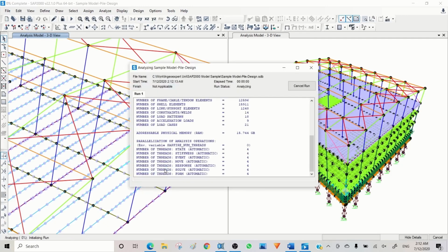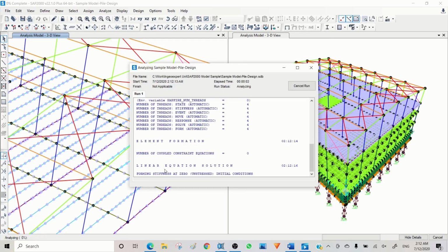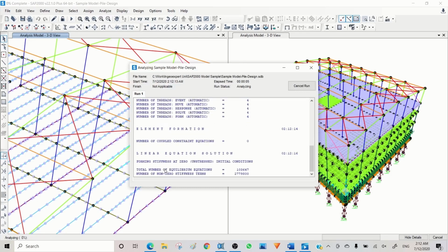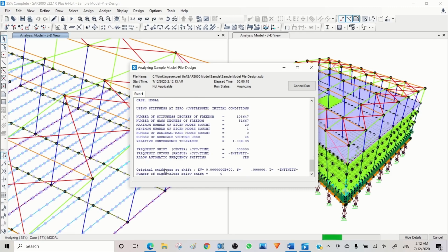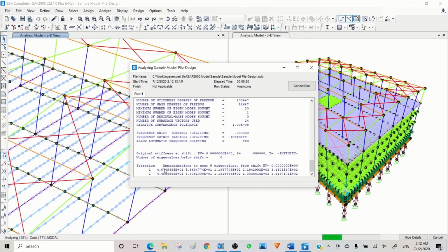So if you want to be conservative in the design of your beam, that's how you can transfer the loads. But in terms of designing the slab, this model will not help you, and you need to have a separate model like a continuous beam and see what the maximum moment of the slab is, and based on that design your slab.